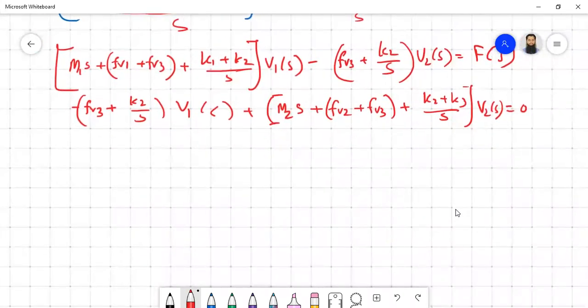So, as you can see, there are two velocities, V1 and V2. So, definitely there will be two loops. Some components will be common between the loops, and those components are nothing but these ones that are common. So, we can write those commons. Okay, so FV is represented by a resistor and K is represented by a capacitor. So this value is FV3 and 1 by K2.